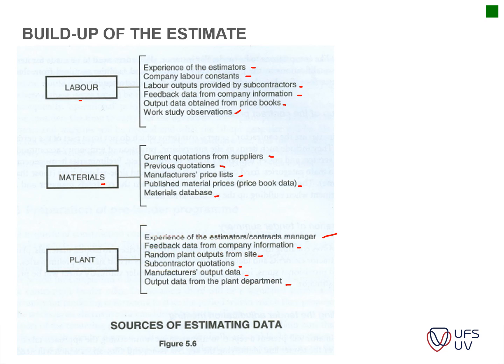So on this project, it will maybe be needed for an hour. It has a cost of 6,000 rand per day, depending on the size of the excavator. And then you can calculate, okay, this will be the cost of excavating this section. Obviously, you will need to take into account that you might need some labor to clear out the excavations, cleaning and leveling them. Is the excavated material staying on site? Is it stockpiled? Is it carted away? That type of thing has to be taken into account.